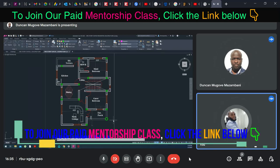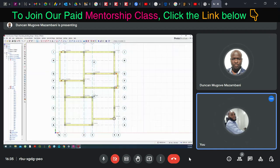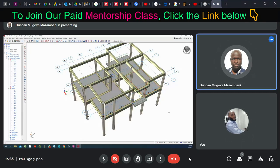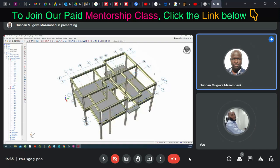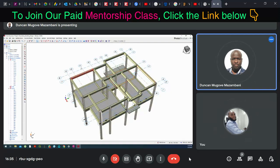Go back to your Protastructure and check your 3D view of what we have just done. Okay, go back to story one. Let's now put beam wall loads, because all the beams on story one have a wall load.